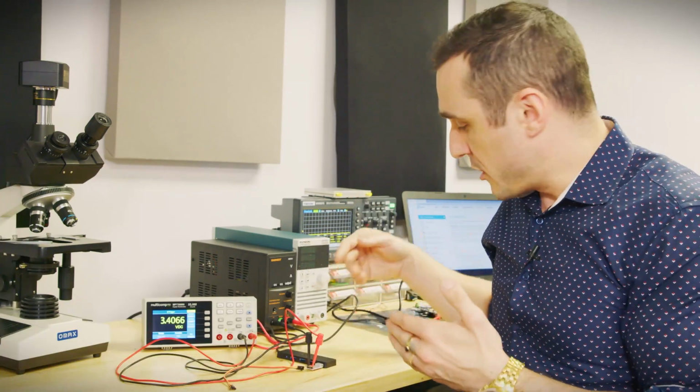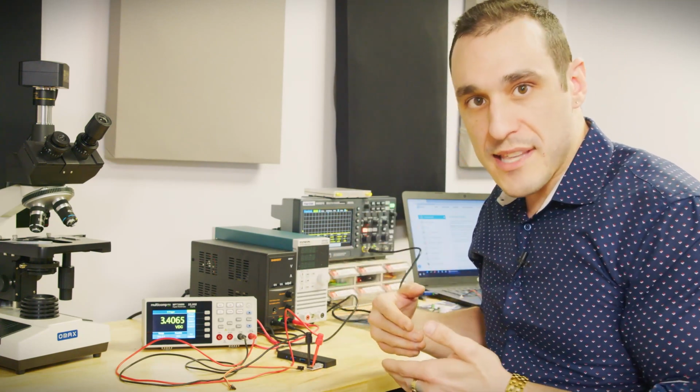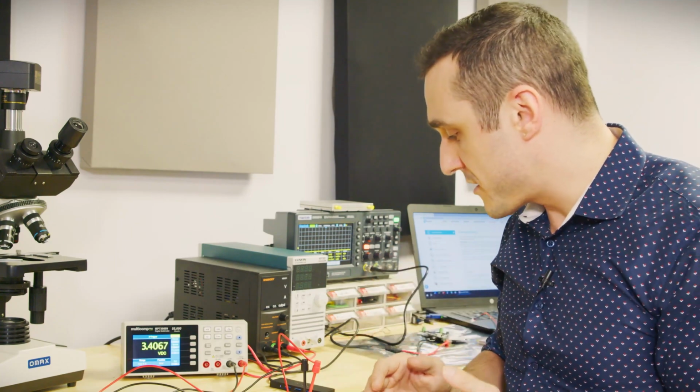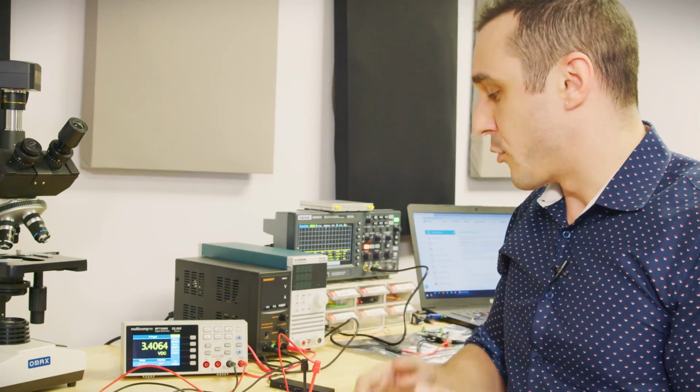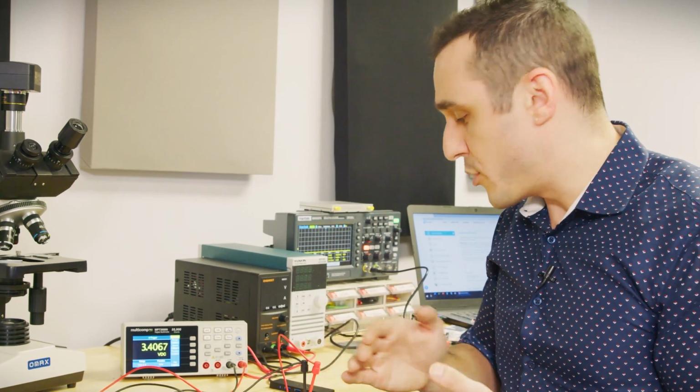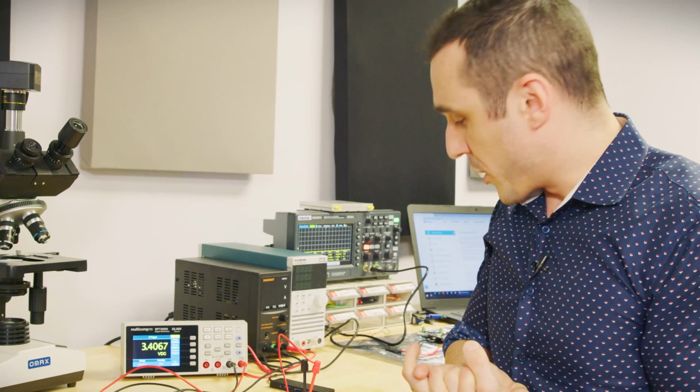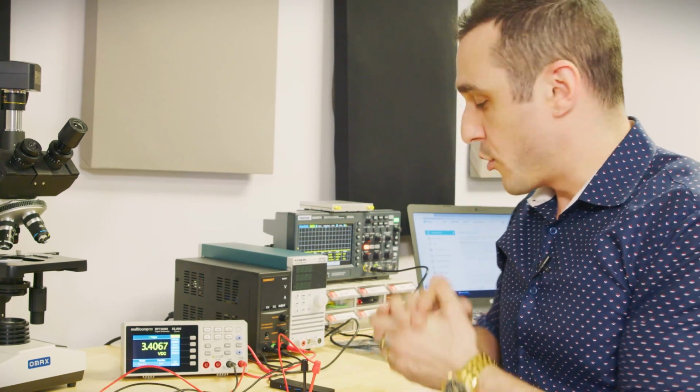One of the big reliability problems with these little modules is that they have zero ESD protection on them. I've shorted out plenty of these by accident, and unfortunately they just don't have much withstand voltage to them, and it ends up breaking the module. So we're going to add some ESD protection onto our custom board.